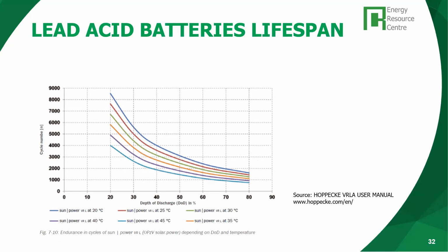In off-grid applications, mini-grids, remember, we're talking about remote areas, remote places. Going there and changing a battery is not easy. Logistics are complicated and very expensive. So it is not a bad idea to oversize batteries a little bit, not in the capacity, but in the depth of discharge, so as to prevent having to change batteries too often.